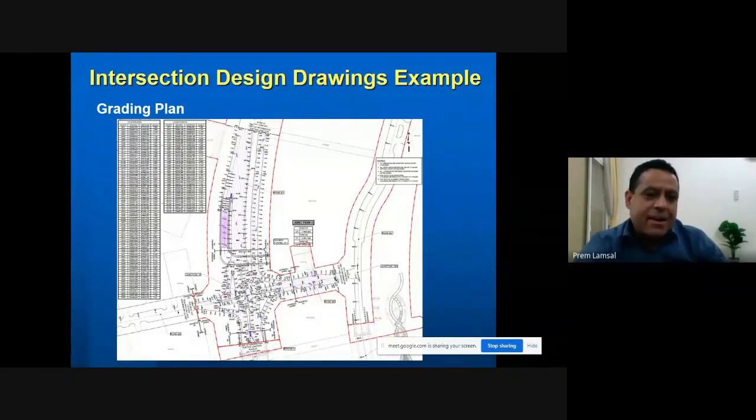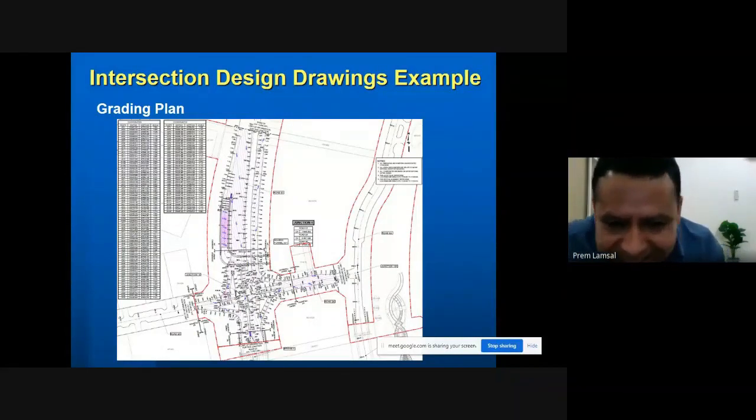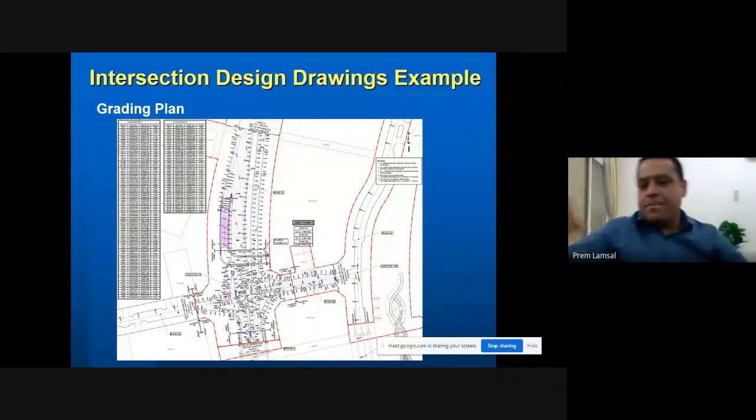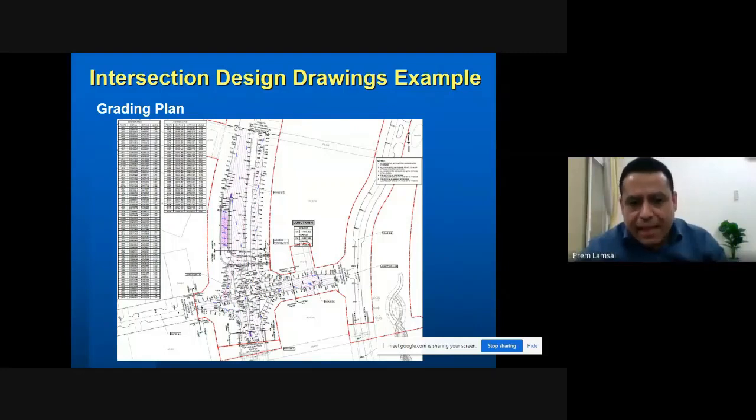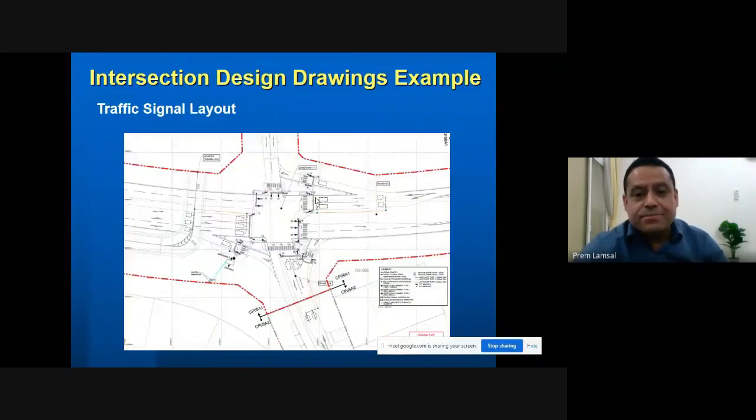And the area will have ponding, there will be pavement issues, some footpaths will be very narrow, bearing width is not constrained, standards are not followed, ramps are not properly placed, and sometimes ramps are very steep. There is no drop curb, for example for wheelchairs and strollers. You can see these kinds of issues. So if you give a clear drawing with a lot of details like this, it's easy when people are constructing, and they will build as per this. This is the standard practice here. I just wanted to share.